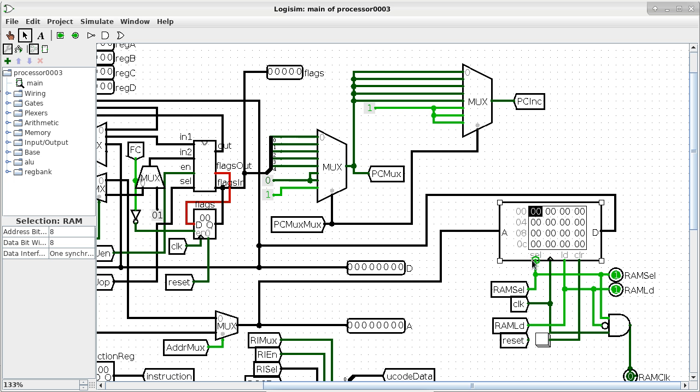Of the control ports, we have the first one. This is SEL, which stands for select. Most industry terminology would call this one CS or chip select, but select works too. If this one is a 1, that means the component is selected, which means, hey, RAM, pay attention. That's what the select line is doing. It's analogous to the enable line of our D flip-flops.